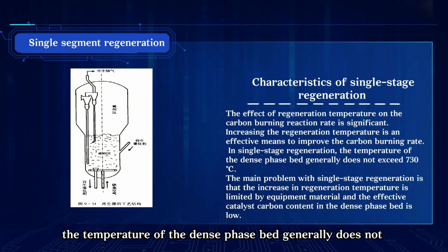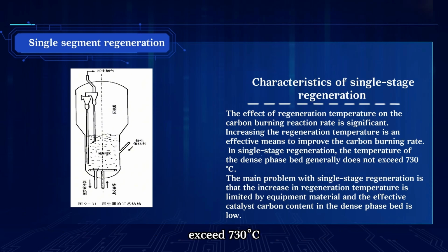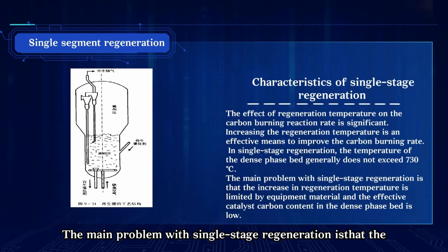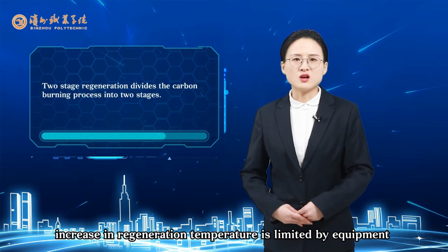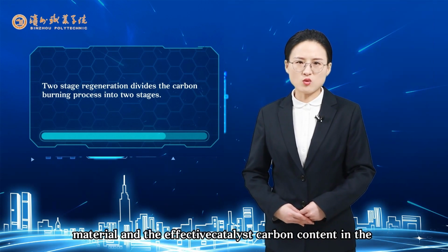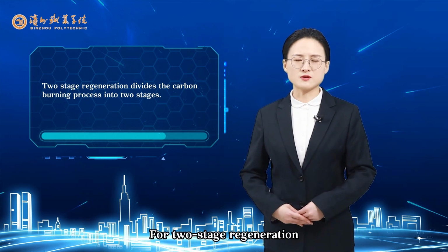The temperature of the dense phase bed generally does not exceed 730 degrees Celsius. The main problem with single-stage regeneration is that the increase in regeneration temperature is limited by equipment material, and the effective catalyst carbon content in the dense phase bed is low.